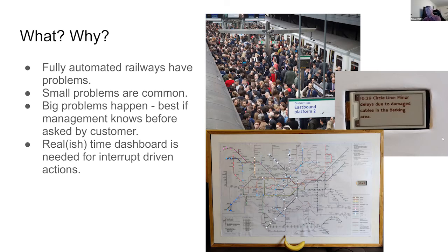Yeah, it's shared power, so power runs all the way through, as does ground. That's fine. If you lose one neopixel, you sort of lose the rest of that chain. But it doesn't normally affect it. You do lose neopixels every once in a while. They just sort of burn out, and all the other ones will still work as long as it doesn't affect the power.